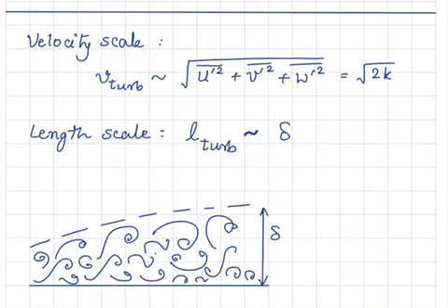But there are a number of turbulence models which are based on an idea of a length scale, which is the thickness of the boundary layer, the thickness of a free shear layer where there is turbulence, and so on. The other thing that goes into such a model is that the scales of turbulence, the sizes of eddies, are not the same everywhere in the boundary layer.